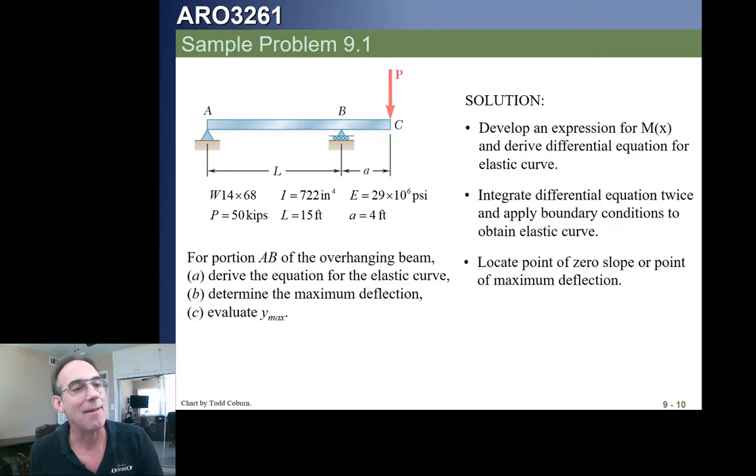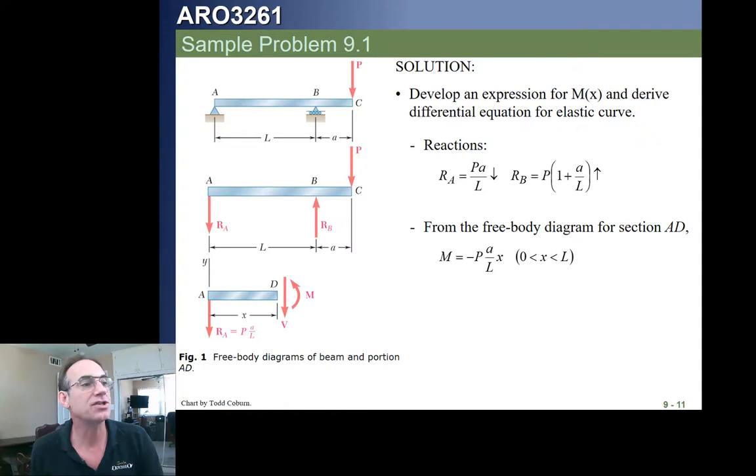Okay? That's what all this says. Okay. Here's how it works. We first calculate our reactions by summing forces and moments, from our free body diagram. We then go ahead and, as I said, this is just taking successive free bodies. This is the first method I presented last lecture.